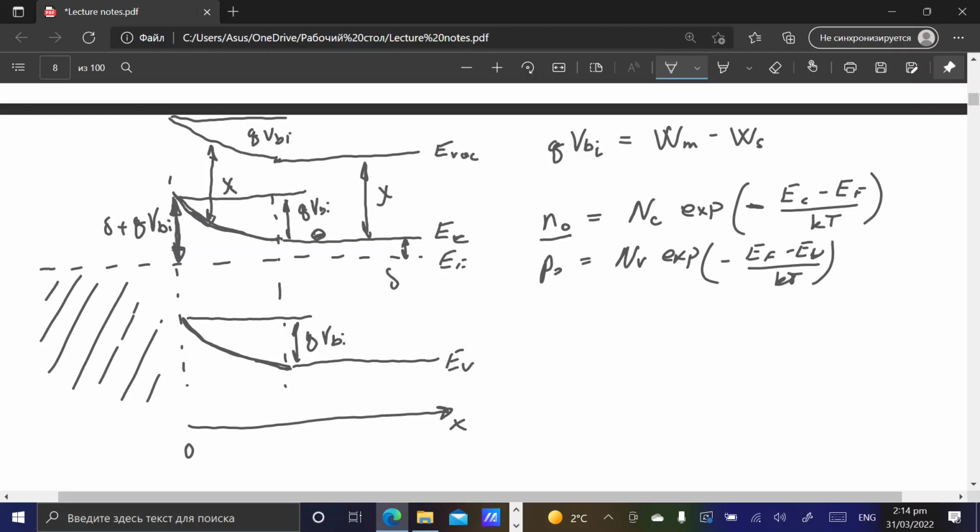So this gap between Fermi energy and top of the valence band is much smaller in comparison to the neutral region of the semiconductor. However, in this case, we still have a larger distance between the top of the valence band and Fermi energy than from Fermi energy to the bottom of the conduction band.